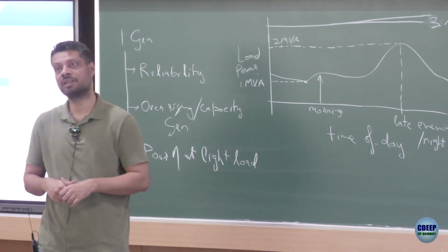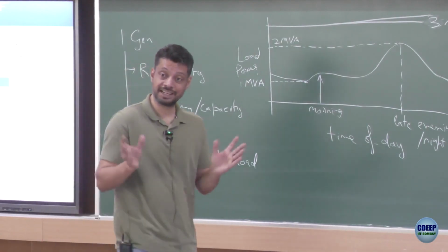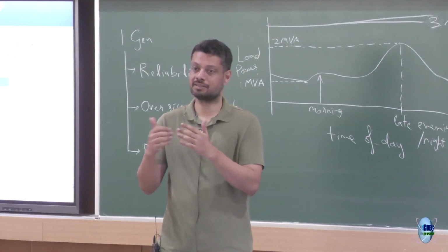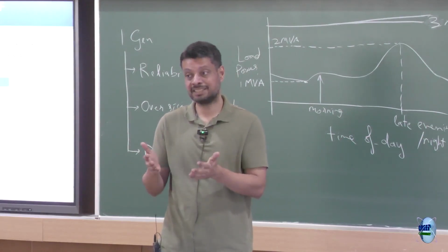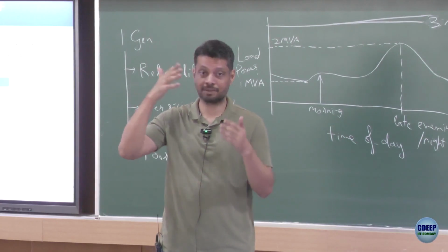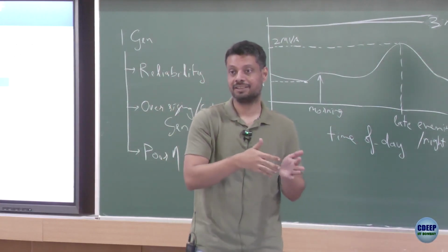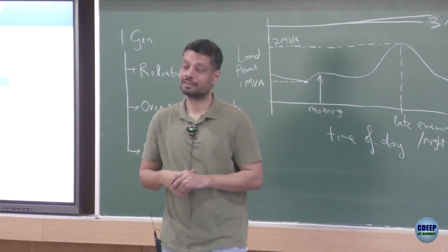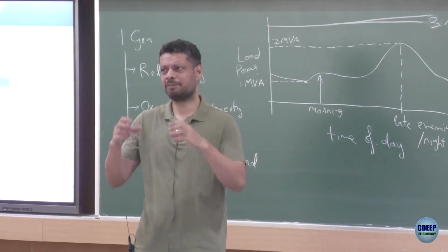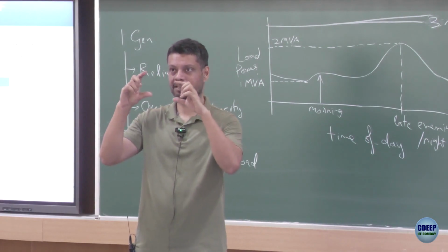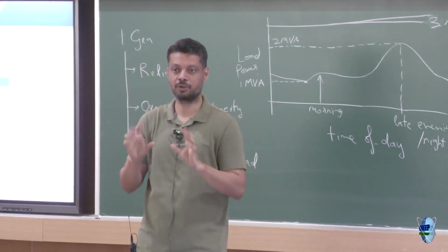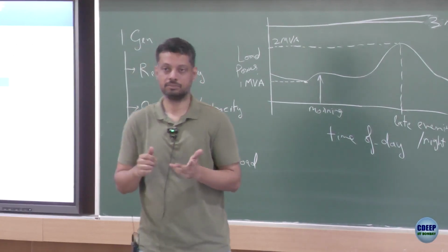No, we are not only synchronizing all the residential, we are synchronizing every type of load. We are connecting every type of load: industries, residential, some residential in colder regions, some in warmer regions. We are just connecting everything together. The average would become lesser and lesser, the delta would become smaller and smaller, as you keep adding more diversity in terms of your load.